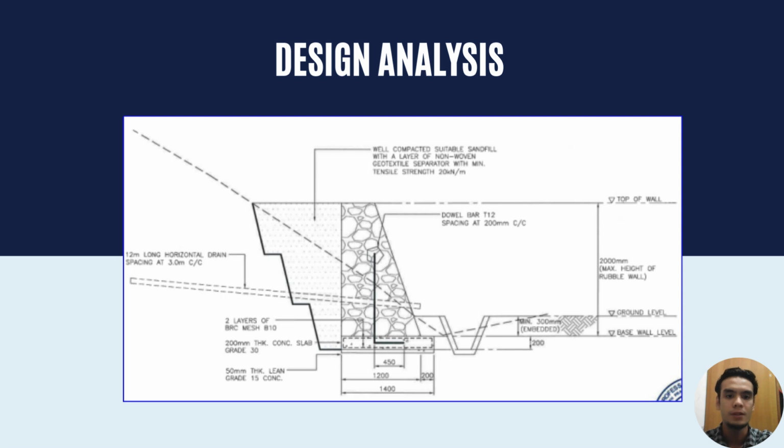For the second one, this project implements a drainage system alongside the retaining wall. A proper drainage system is critically important as it prevents water accumulation behind the wall. Accumulated water can create hydrostatic pressure, which can destabilize the wall. Drainage solutions like weep holes, perforated pipe, or French drain ensure water is directed away from the wall, maintaining its stability and longevity.